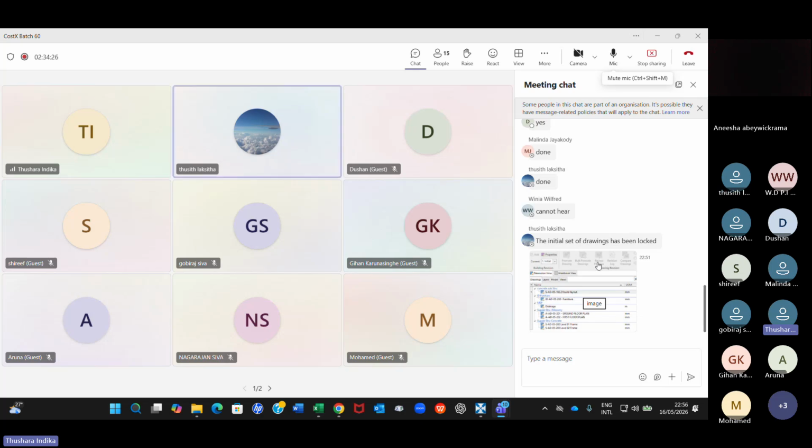When you compare the drawings, you understand the affected dimension groups. So you select the affected dimension groups, and then you click on revision one, and then you update all the quantities basically.